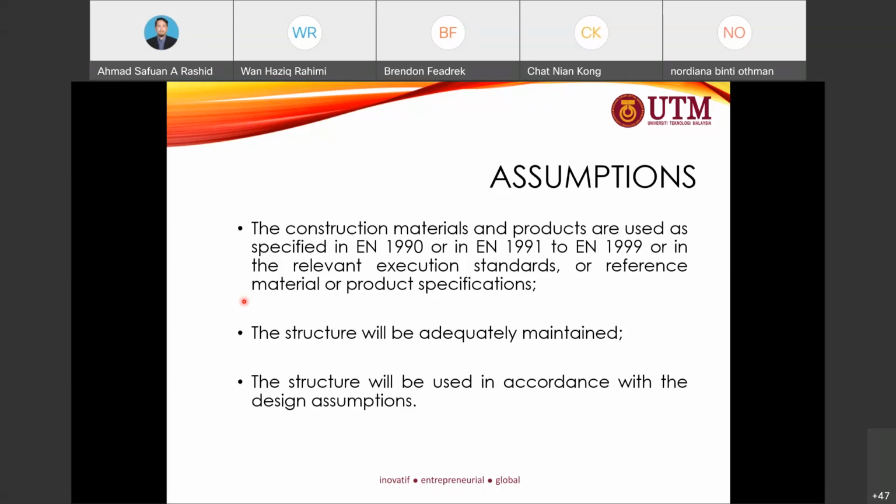Compare that if we want to build a double-storey or high-rise building, we should have very good and extensive soil investigation work, where we can use all the input in the design. So it depends on the purpose or the function of the building.